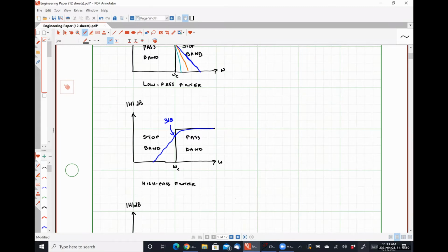So if you're trying to electromagnetically shield something, like with a copper barrier, and you want to make sure that it's acting as a good shield, you would apply a signal to one side of the copper barrier and your antenna on the other side should be picking up that same signal, but 60 decibels lower for that shielding to be considered good. So it's all relative, but there are certain metrics within certain fields that are used.